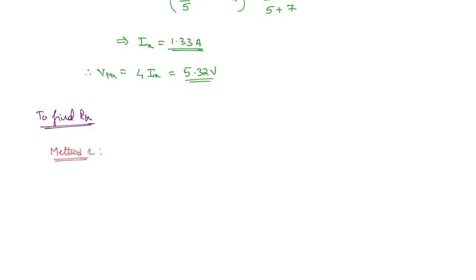Whatever circuit you wish to convert into the Thevenin equivalent, take it as a two-terminal network. So this is A and B. Now if you connect a 1 ampere source here, and take this voltage as VAB, then what will be the Thevenin's resistance here? Basically Thevenin resistance is nothing but the equivalent resistance of this entire network, so you can replace the network with the Thevenin's resistance, right?